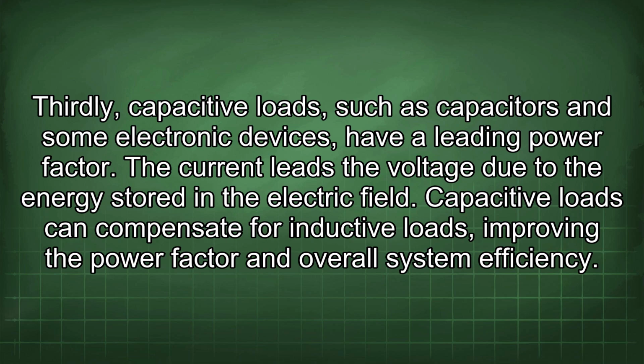Thirdly, capacitive loads, such as capacitors and some electronic devices, have a leading power factor. The current leads the voltage due to the energy stored in the electric field. Capacitive loads can compensate for inductive loads, improving the power factor and overall system efficiency.